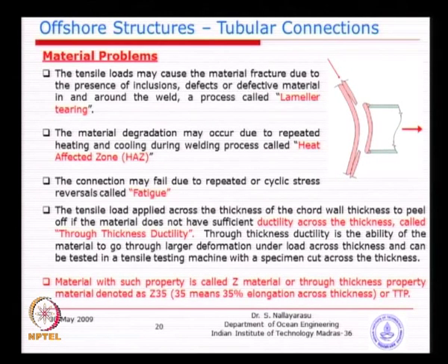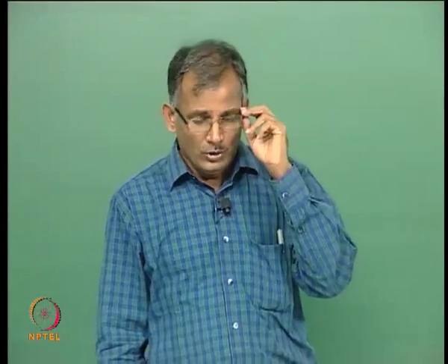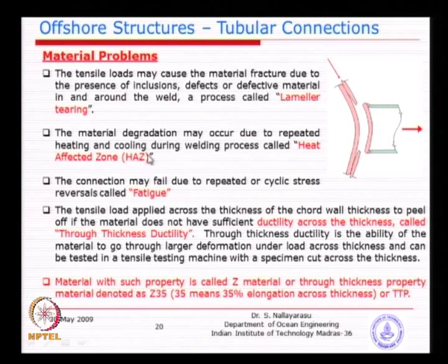So, at that time the material characteristics deform and get weakened, basically because cooling is faster than necessary. For example, whenever you are welding at 1000 degrees, you should not cool it very quickly; it should be slow cooling. If it is quicker, then brittleness forms and it can actually crack even immediately after welding. So, the heat affected zone is one of the potential problems we worry about, and also